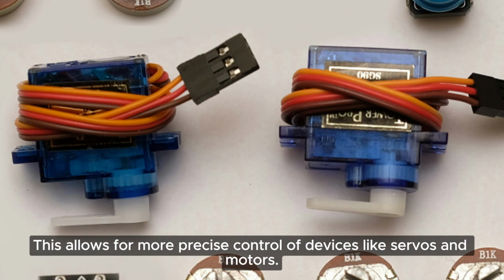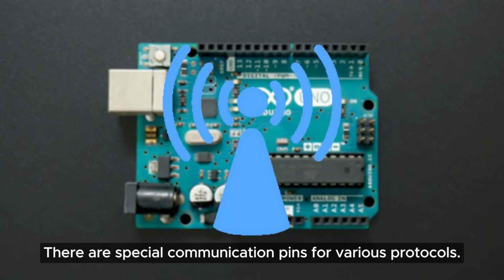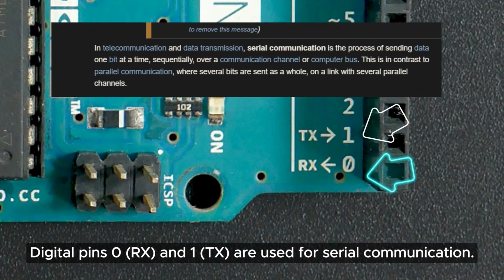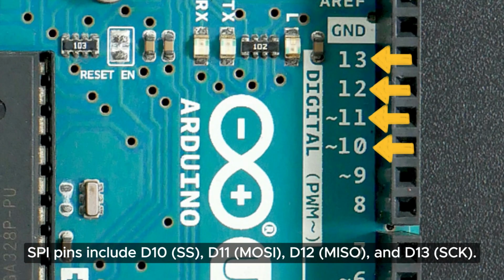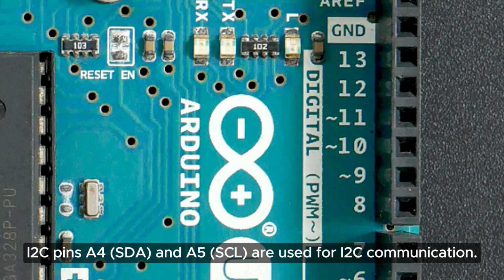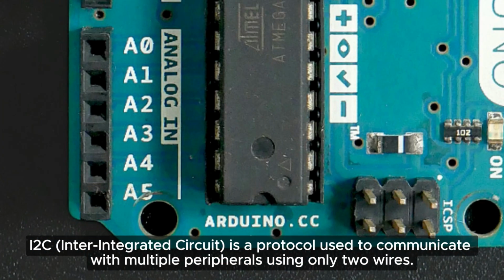This allows for more precise control of devices like servo motors. There are special communication pins for various protocols. Digital pins 0 (RX) and 1 (TX) are used for serial communications. SPI pins include D10, D11, D12, and D13. SPI is a communication protocol used for short-distance communication. I2C pins A4 and A5 are used for I2C communications. I2C is a protocol used to communicate with multiple peripherals using only 2 wires.